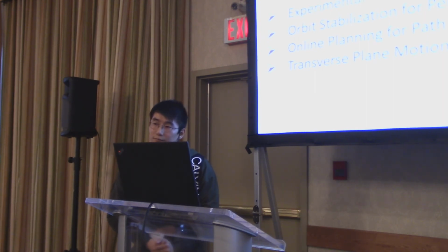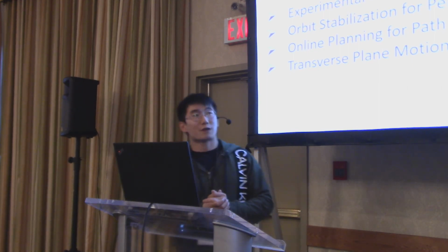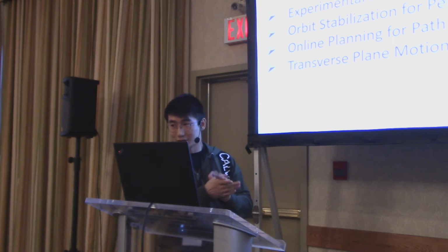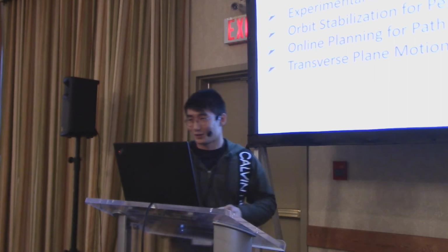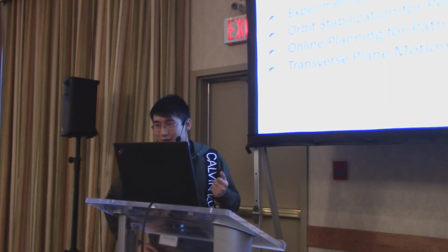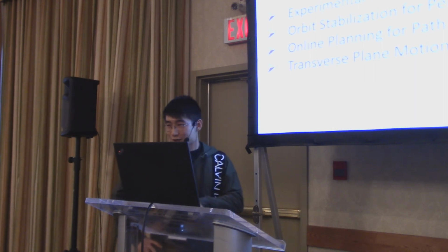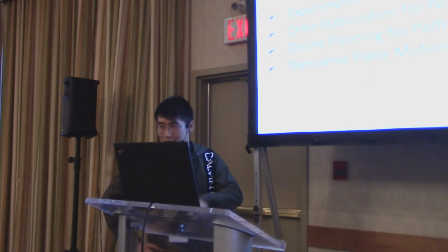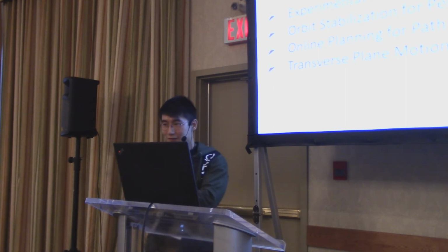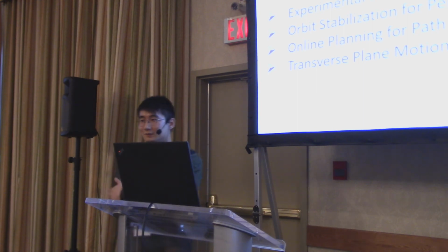But it seems like if you're just using foot placement, you don't have any more freedom, right? It seems like it'll interfere. So I'm not doing foot placement for the yaw, obviously, because you're not going to get that. There's yaw at the hip for the robot, so that's where you plan that motion. You don't place the foot for the yaw. You use the hip yaw to do the yaw. Okay, excellent.